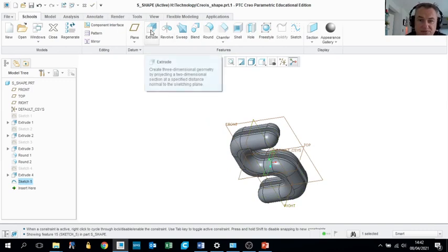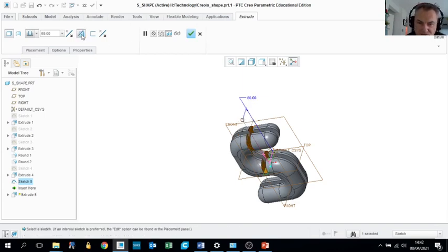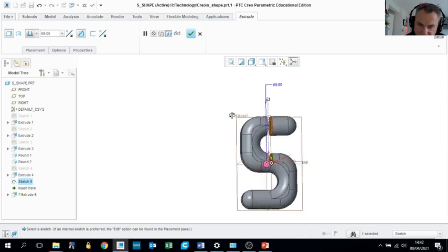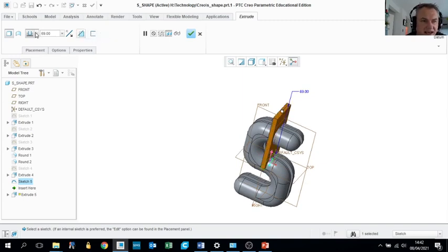I'm going to press Extrude, and you will see the solid object appearing through the model. Remember, if I click on this, it will remove material. Okay, so you can have a lot of fun experimenting with this tool. But if I'm going to put it back in, if I go and do the extrude both sides of a sketch plane, click on that, very useful, and then go through the model that way, and then remove.